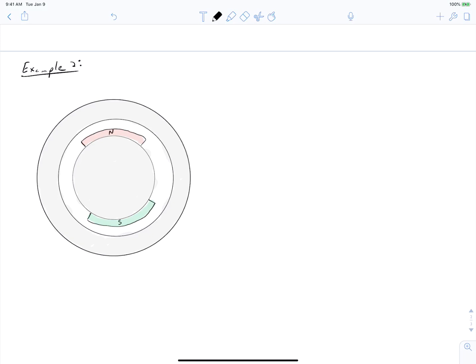What we're going to do is assume that the permeability in our iron is equal to infinity in both the rotor and the stator. So that's in the iron regions. In the air gap, of course, we have a permeability of mu naught, and then our permanent magnets have whatever permeability that magnetic material has. Typically, it's approximately mu naught. And what I want you to do is first sketch the magnetic equivalent circuit schematic.